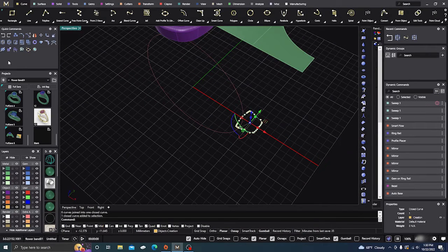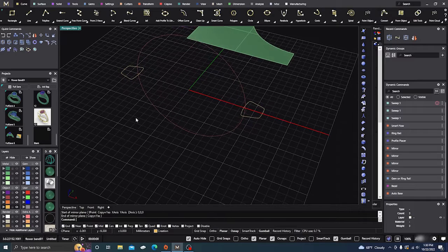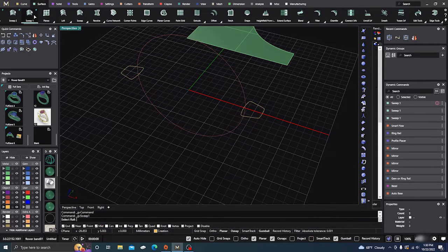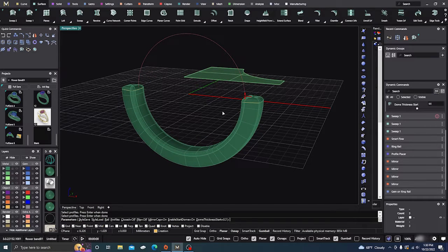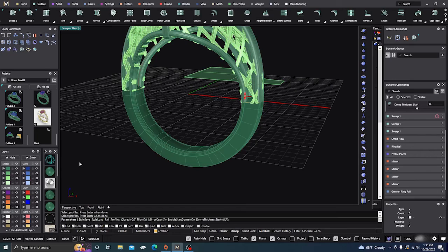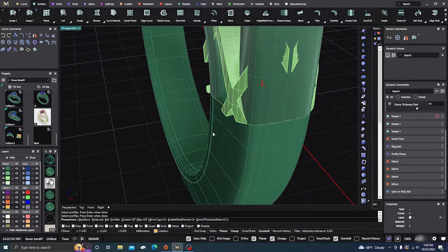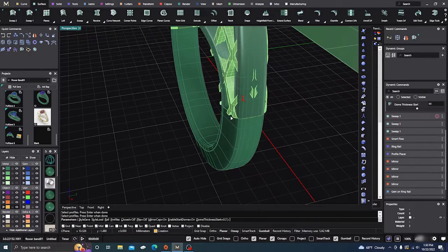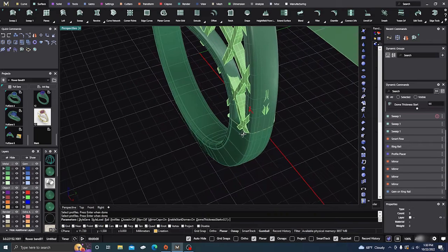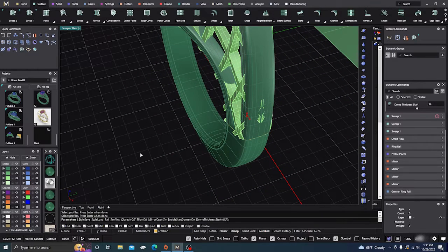Okay, and then I'll take it, mirror it to the other side, F4, hold down shift, and let's go ahead and do a sweep real quick. Sweep 1, should have checked those seam points again. I didn't. It came out okay. And we'll drag that up just a little, and we'll turn these back on. Okay, so it's still just a little bit outside my rail there. Okay, so let's back out of that again.